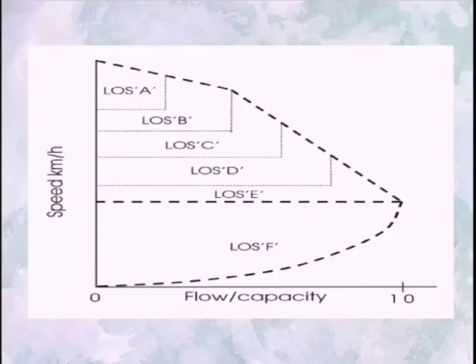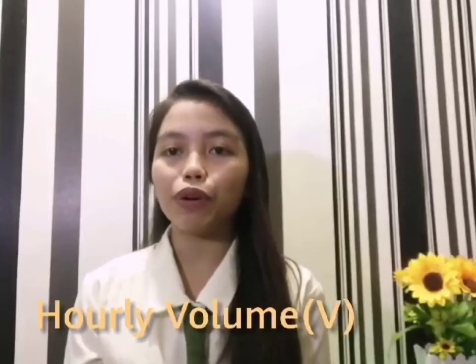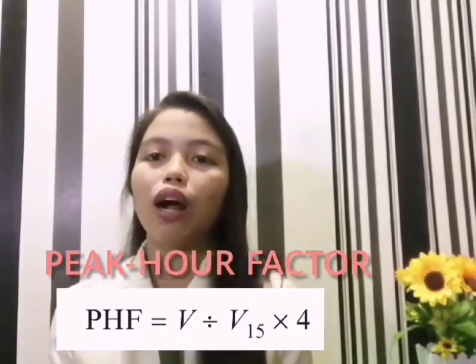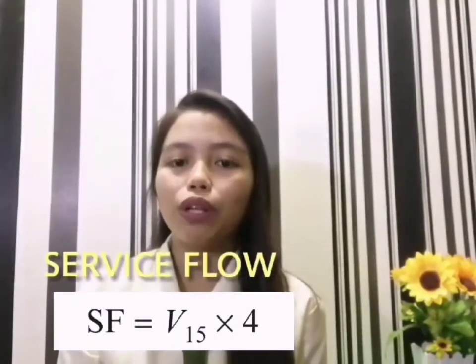In this figure, it shows the conditions and their associated speeds and flows. It is the linkage between level of service, speed, and flow capacity. In order to determine the road's level of service, a comprehension of the relationship between hourly volume, peak hour factors, and service flow is needed. Hourly volume is the highest hourly volume within a 24-hour period. Peak hour factor is the ratio of hourly volume to the peak 15 minutes enlarged to an hourly volume. Service flow is the peak 15 minutes flow enlarged to an hourly volume.